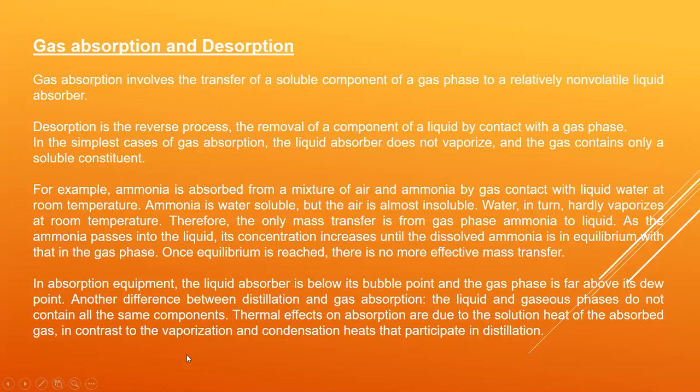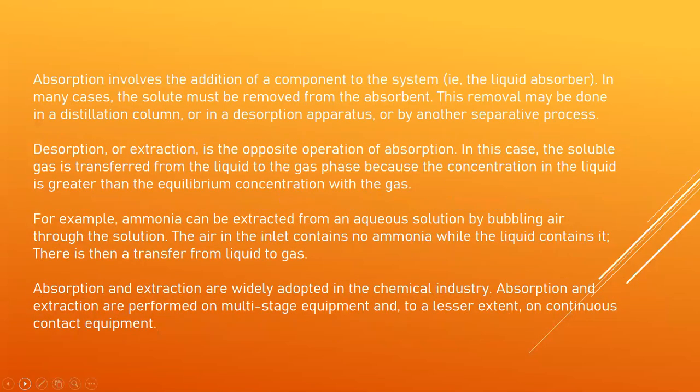It's always a starting point when I discuss distillation and gas absorption that I distinguish one from the other. Because later on, when we design the equipment of these two, there is great similarity in the manner in which they are being designed. But as to the characteristics of the phases present during the process itself, they're very different, so they are to be treated very differently. Now, absorption involves the addition of a component to the system, that is, the liquid absorber.